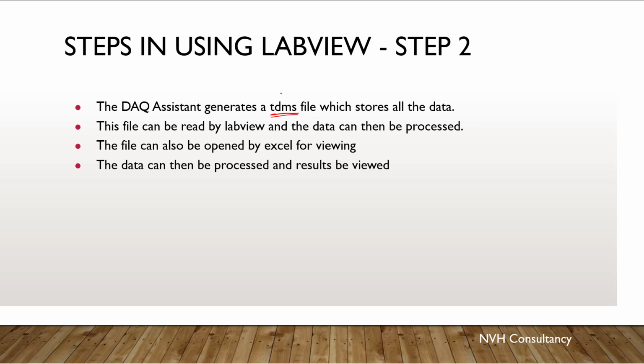The need to go for the TDMS format is that the data that you are streaming continuously through your NI9234 device is very high resolution data. Suppose the data that you are streaming is normally in the range of 51 kilosamples per second, so you are streaming about 50,000 data points per second.